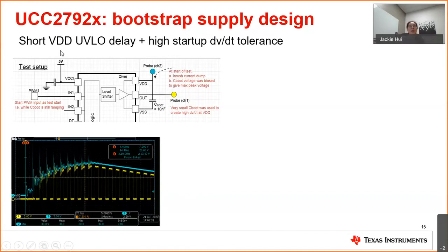So what I show here is a test setup. Basically, we want to test how robust this driver is against a high dV/dt during startup, as well as what the UVLO delay is, which will affect how soon your system can start switching.